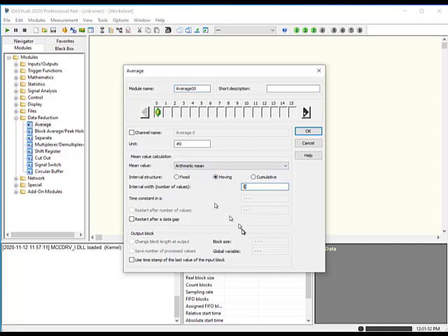And you can do a moving average, for example, over, let's do 16 samples. And so the input and the output time stream are the same. What will be different is that the output value will be a moving average of the previous 16 values.